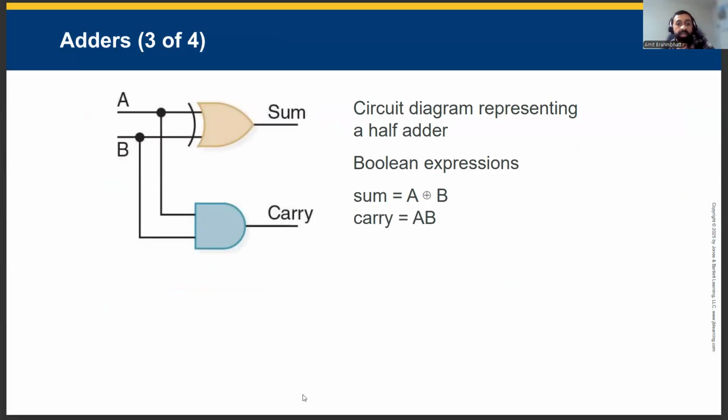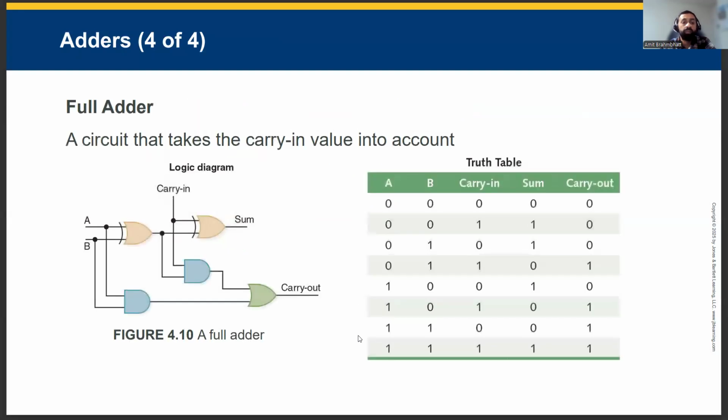The half adder circuit captures those rules. Sum equals A XOR B, implemented with XOR, and carry equals AB, implemented with AND. That pairing mirrors our earlier gate definitions. By wiring many half-adder-like stages and handling carry between bits, we approach full multi-bit addition.